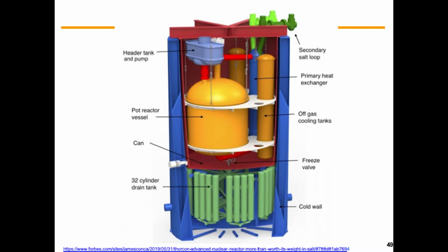So they can use the molten salt reactor experiment as a reference in their licensing. That's their approach. So this would be the reactor vessel with the pump and the heat exchanger. The heat exchanger is horizontal instead of vertical as in MSRE. They have the drain tank, so it's more closely integrated than in the case of MSRE. It's kind of optimized and rearranged, but it's really just a bigger MSRE.